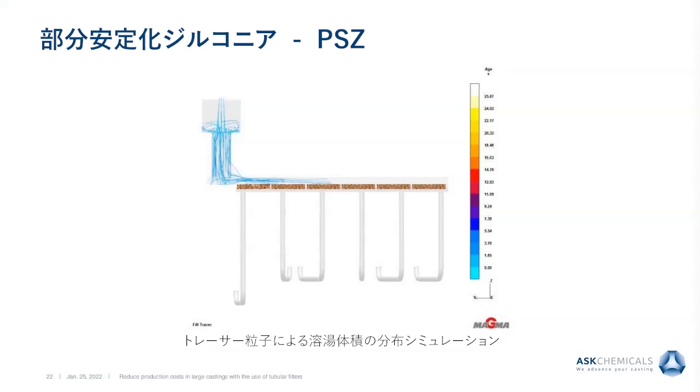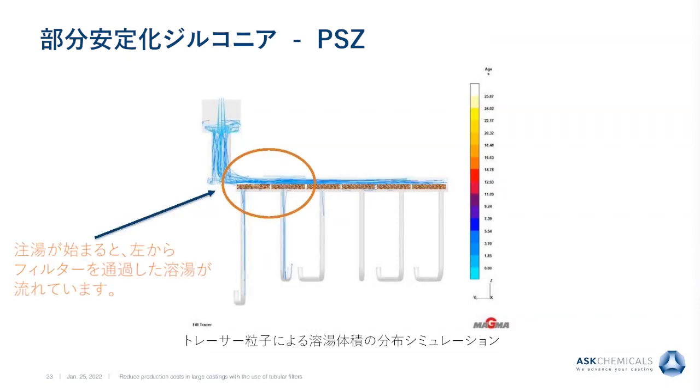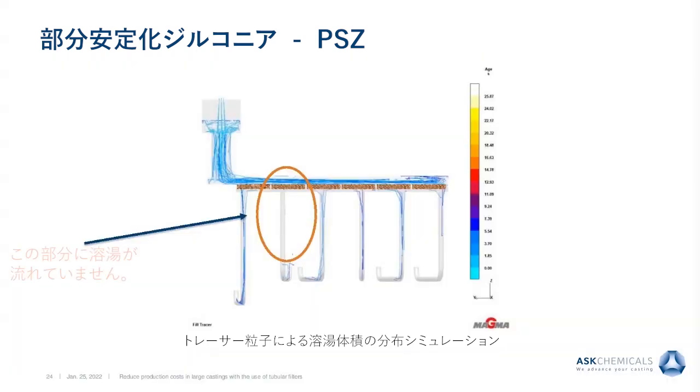When we start with the normal casting process, the runner is filled more and more, and then the first melt is running into the runners to the ingates, and then we see that the system starts really with a different distribution of the metal. This is reinforced by the lack of filter support at the joints of the filter. Also, when inserting the filters in sequence, filter bits or ceramic inclusions can break off from the surface during contact and subsequently pass into the mold.